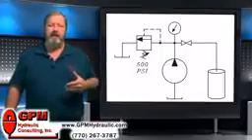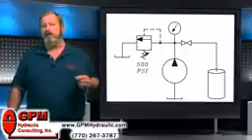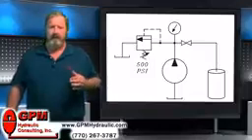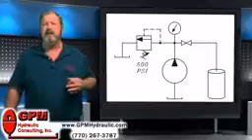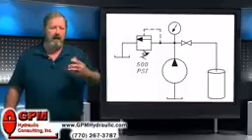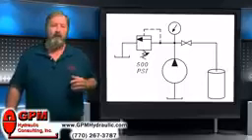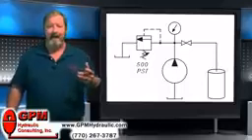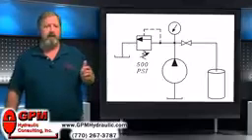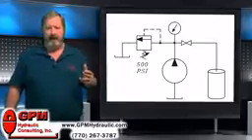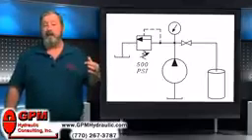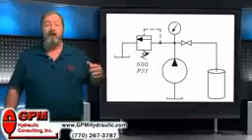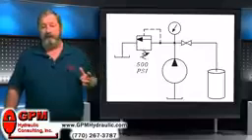That means that our relief valve is a normally closed valve. On hydraulic schematics, normally closed means that it normally blocks flow. Unlike on an electrical schematic where a normally closed electrical switch allows flow, on a hydraulic schematic, a normally closed valve normally blocks the flow and something has to happen to open the valve and allow flow.